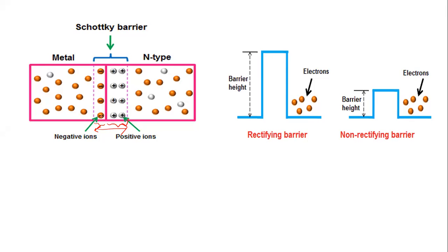Okay, the advantage here is the difference between a normal p-n junction and the Schottky barrier junction. In this Schottky junction, that is a metal semiconductor junction, the depletion width is mostly within the semiconductor side. The depletion width on the metal side is extremely thin, always.